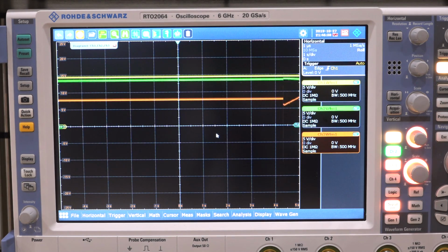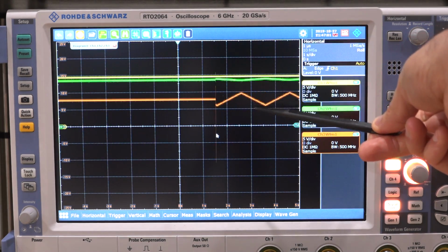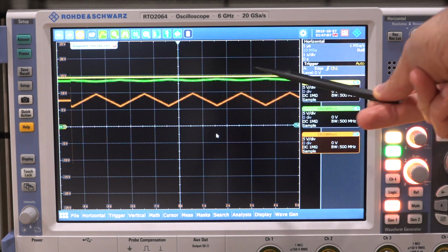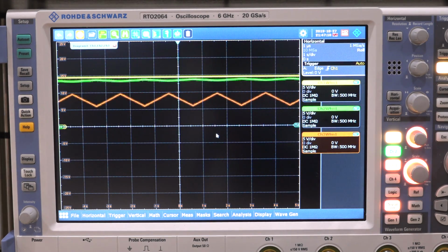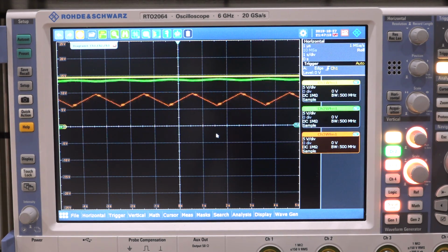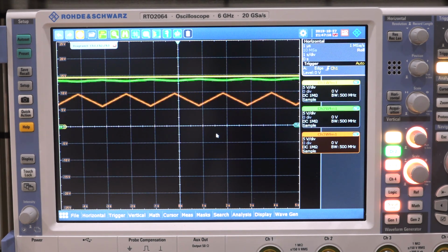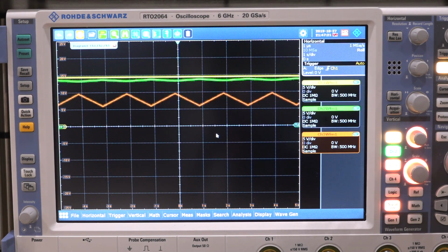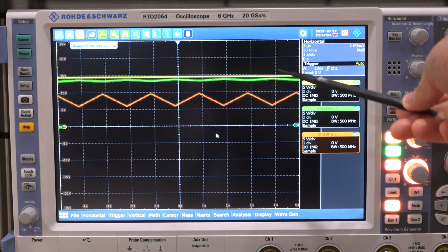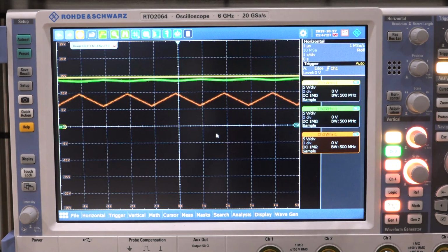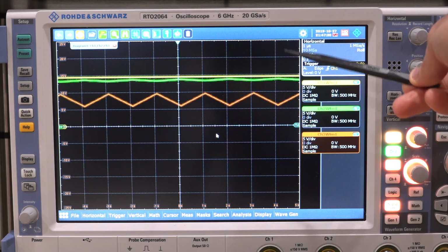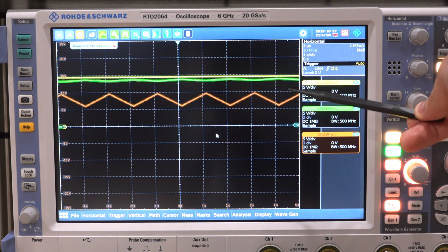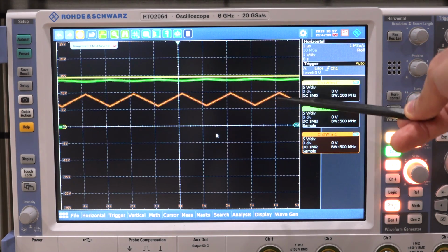So here's the FM modulation, and check it out. There it is. This tells us that on channel 3, we're looking at the FM tuning port of the VCO directly, because you can see the triangular wave that I apply, the system is following that and compensating for it by tuning the VCO such that the PLL remains locked to the reference coming in. If I look at the output frequency of the system, it's going back and forth with exactly the same amount. So you can see that the yellow line over there, even though it changes when we tune the instrument, doesn't really change here, meaning that that must be our digital pre-tune. And there is the green one, I'm not exactly sure what that is, because it seems to be a combination of the digital pre-tune and the FM tune of the VCO.